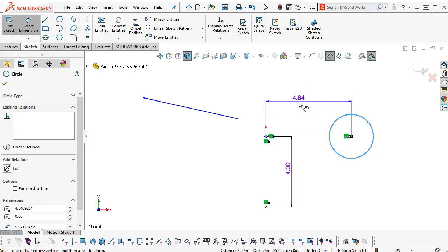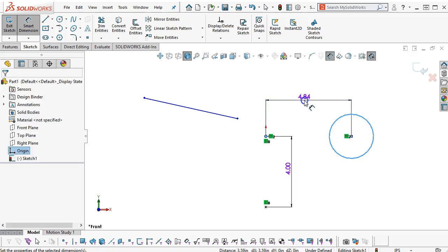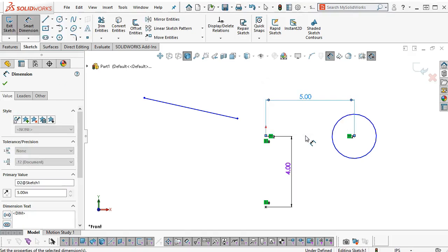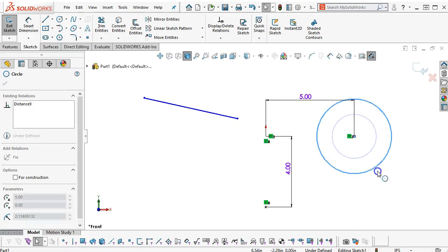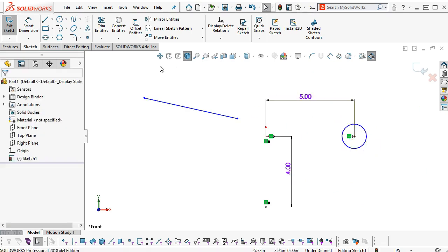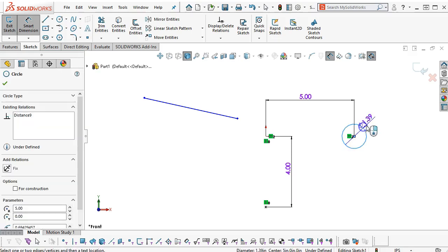and my first choice is going to be to use another relation called coincident, but I'm focusing mainly on the points and the dimensions at this time, so we'll stay with that. All right, so 5 inches, the center point goes to black. The circumference is still able to move, and if we get it small enough to where we can't see it, it should still be there, but not anything functional. Maybe a blue dot that we can zoom in on